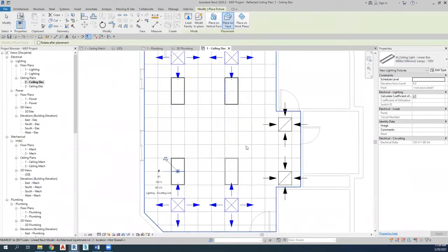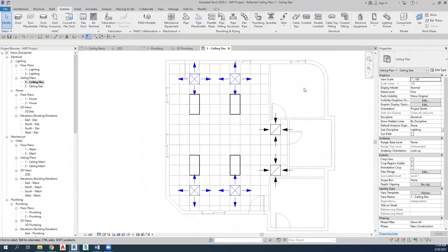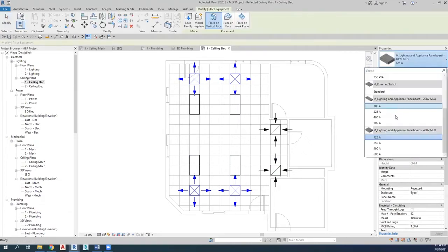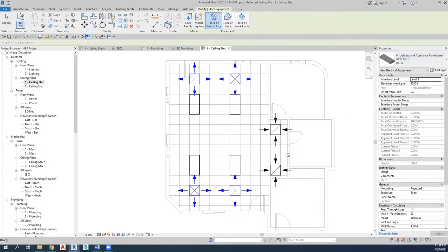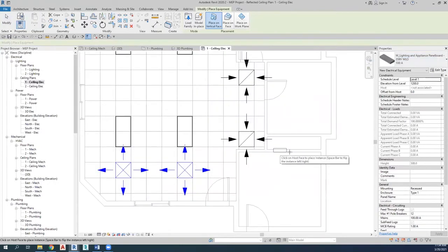We will now be placing the 4 lighting fixtures exactly centered as demonstrated. Perfectly aligned with the diffusers. We will now be adding the panel, and give instructions to Revit that the 4 lighting fixtures will be taking their power from this panel board. Selecting electrical equipment, we will be using this type of panel board, and placing it in this electrical room.